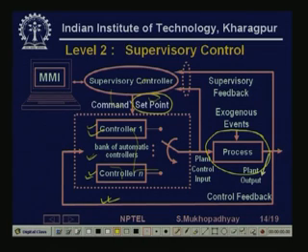So, that command comes from the supervisory controller. So, it gives various kinds of commands. For example, suppose there is some accident, or there is some malfunction in the equipment. Immediately you have to do emergency shutdown. So the supervisory controller must understand that there is a malfunction. How does it understand? Because it also gets the process inputs and outputs.